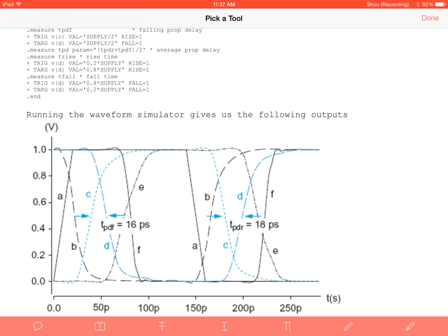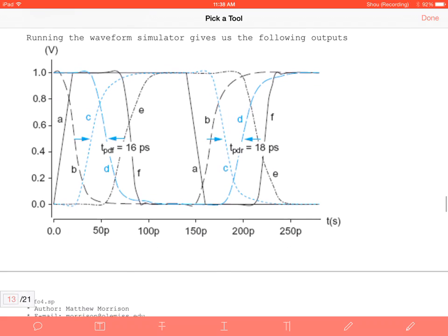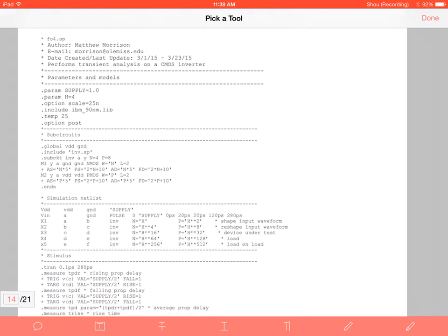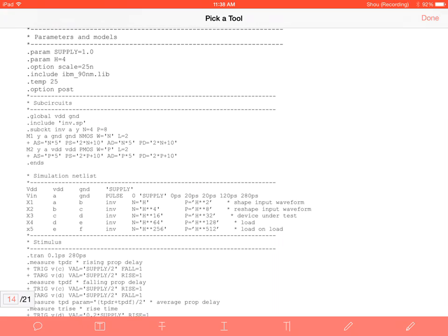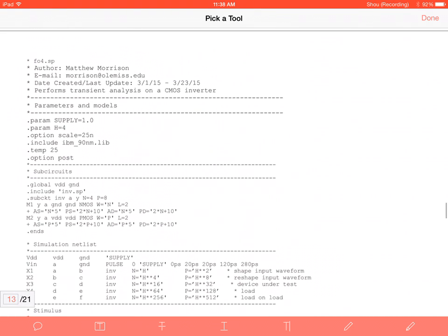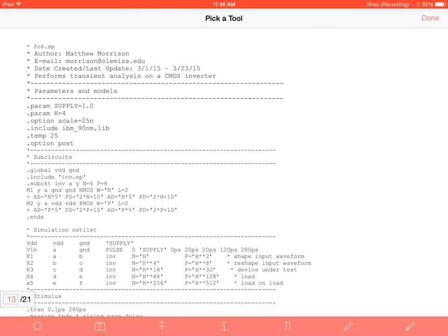So you can actually use the SPICE deck. Now, up to this point through section 1 through section 6, we've learned our theoretical optimal circuit. Now we're going to go into code and actually run it to make sure it works. And so now I've put the entire code together. You guys have now written this SPICE deck. This should all make sense by now. Does anybody have any questions about this?